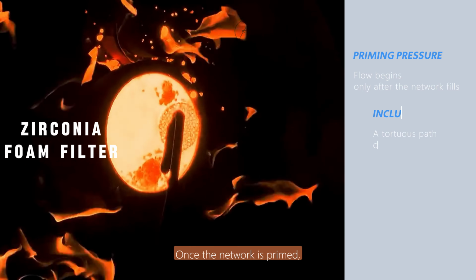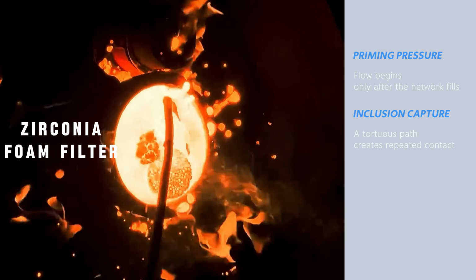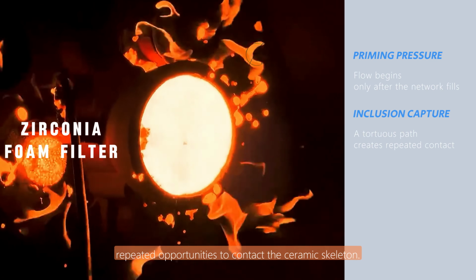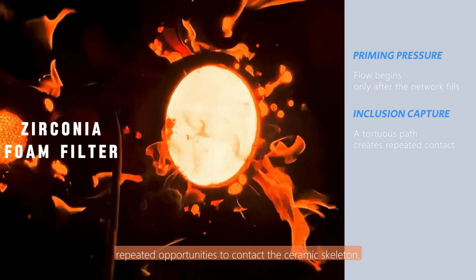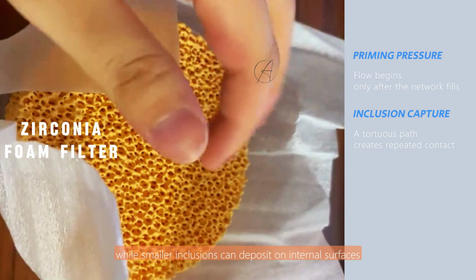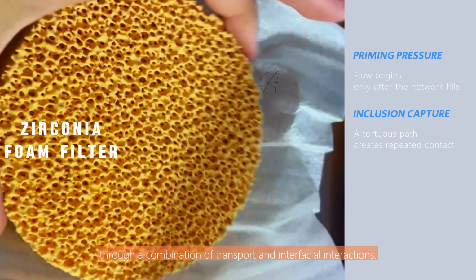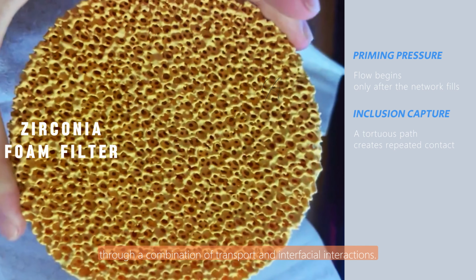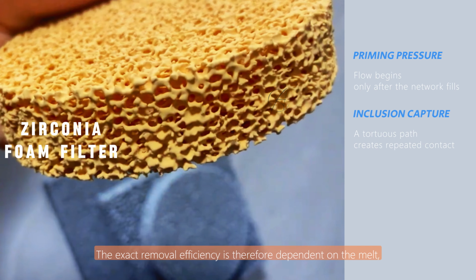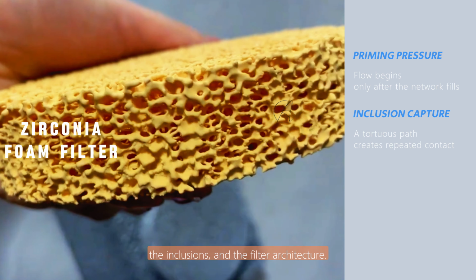Once the network is primed, inclusions do not experience a single straight opening. They encounter repeated changes in direction and repeated opportunities to contact the ceramic skeleton. Larger particles may be intercepted mechanically, while smaller inclusions can deposit on internal surfaces through a combination of transport and interfacial interactions. The exact removal efficiency is therefore dependent on the melt, the inclusions, and the filter architecture.